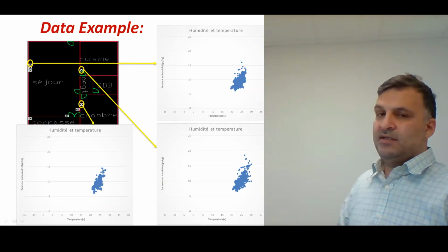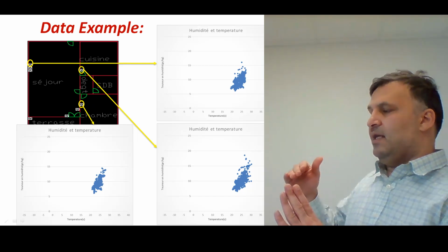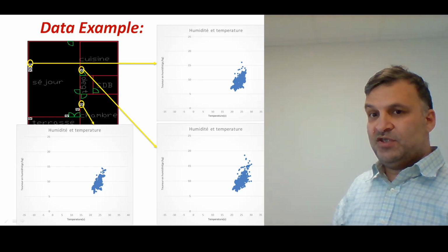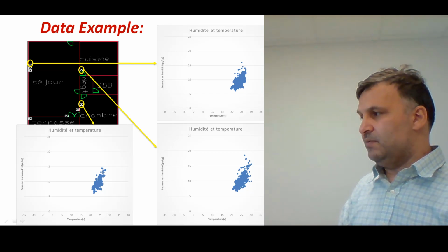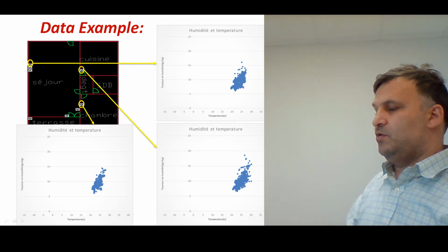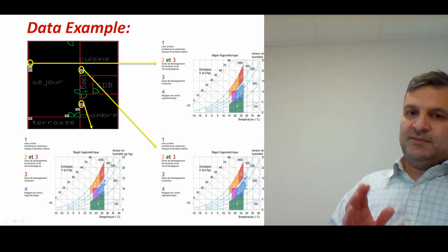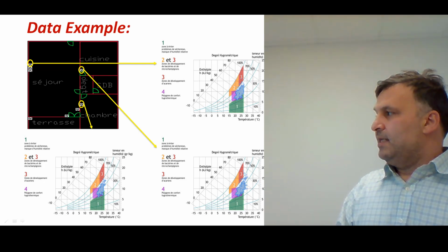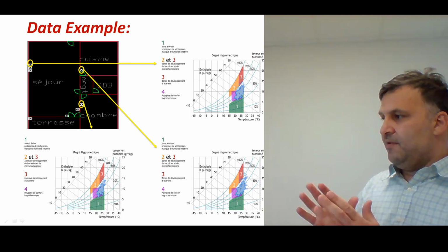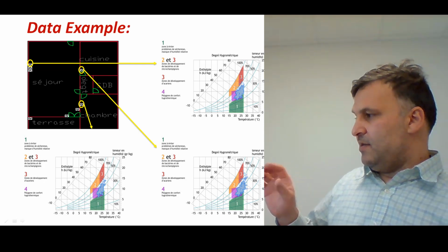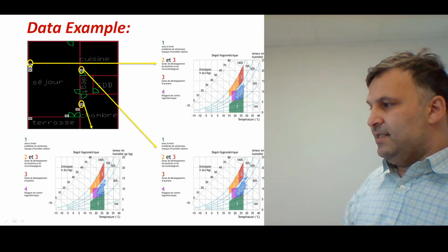and we can use all the opportunity of data analysis. These diagrams, for example, show the relationship between the humidity and the temperature, and it is a very important measurement regarding the comfort and the health in an apartment. So it is accumulated values during 1 month or 1 year, and we can project this accumulated value in the reference diagram of the indoor health, and we can see that our values are in the violet zone, most of them, which is healthy.